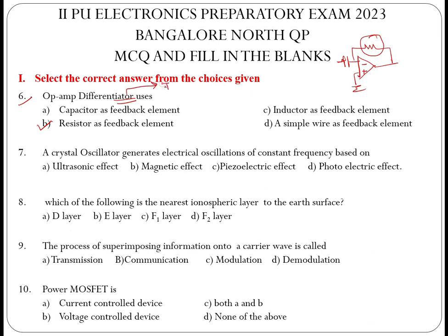Instead of differentiator, if suppose integrator is asked, it is just the reverse. That is, resistor will come to the input and capacitor will be connected to the output. So this is for integrator. Here two questions can be asked in this way.